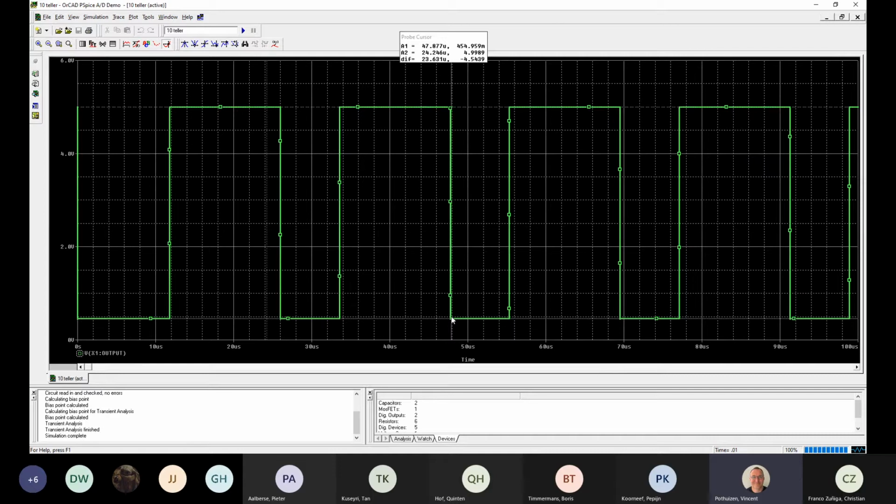Okay. So, they call it the time for one period. The frequency equals 1 divided by the time of one period. So if you know the period is the time it takes for one waveform, and you measure that, you know the horizontal values, the x values in microseconds. So if you subtract, what's the value on the right? 68 something, 69. You can look at the probe cursor window.